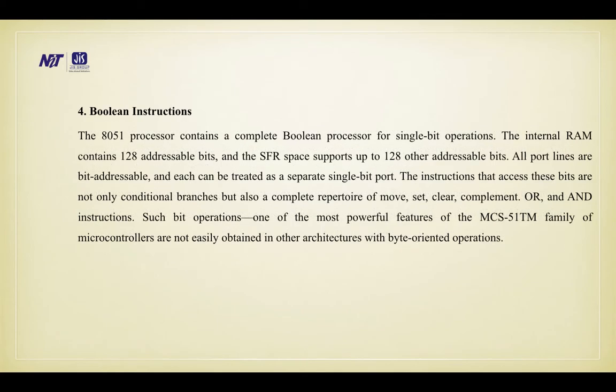Boolean instructions. The 8051 processor contains a complete Boolean processor for single bit operation. The internal RAM contains 128 addressable bits and the SFR space supports up to 128 other addressable bits. All port lines are bit addressable and each can be treated as a separate single bit port.